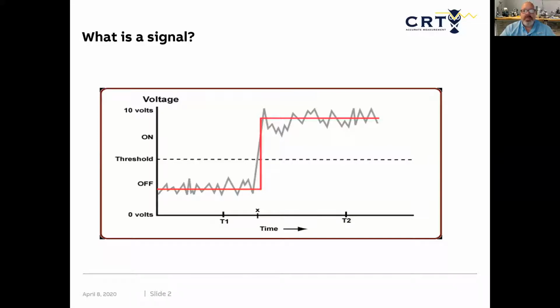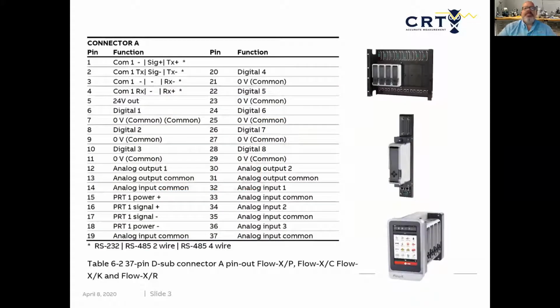I'm just looking for the FlowX is just looking for that signal to go above and below that voltage threshold. As long as I see that and I know what I'm referencing against, then I can determine in diagnostics whether the voltage is actually getting above or below that. So in the FlowX, we have our wiring diagrams, or pinout connections, and they're different based upon